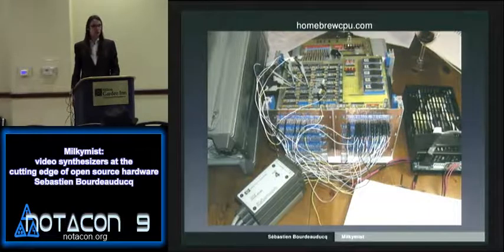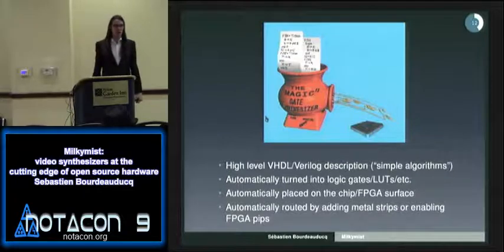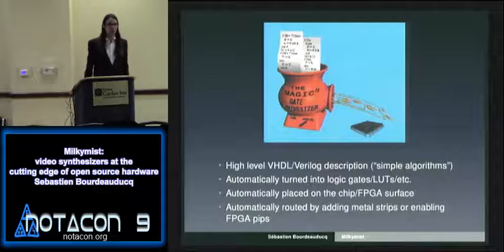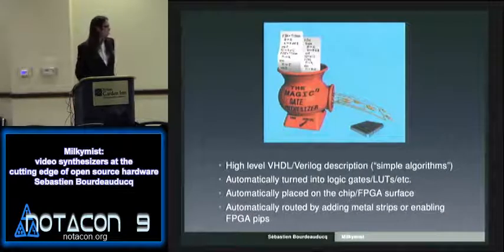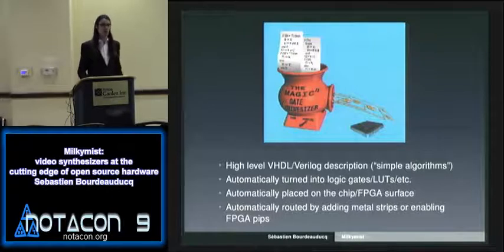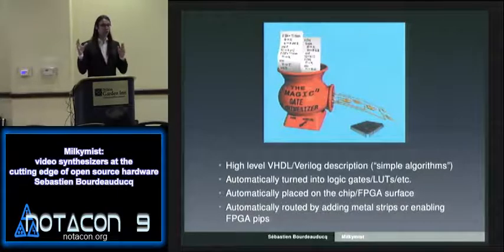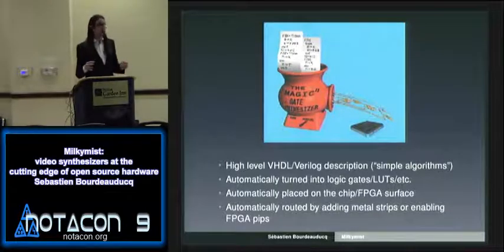So to address the first problems, modern chips and modern logic designs use what are called hardware description languages. So there is VHDL or Verilog. They are the most prevalent languages these days. And what you would do is describe the behavior of your logic using a simple algorithmic description. For example, you can have variables, and then you can assign a logic equation to that variable. You can have conditionals, and when you put that into the software, it will process all the conditionals and logic equations into whatever you want.